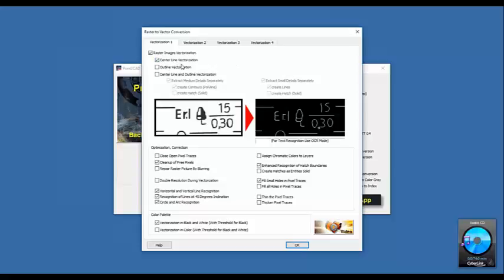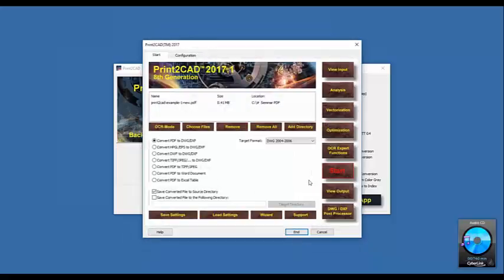Mix the vectorization. Let's make the vectorization for long pixel traces as a center line, and outline vectorization for medium and small details. And I tell you a little bit more: create hatch for the small details. I have not activated any optical character recognition here, and maybe it's enough for me, okay? So let me check now how the drawing looks after the vectorization.